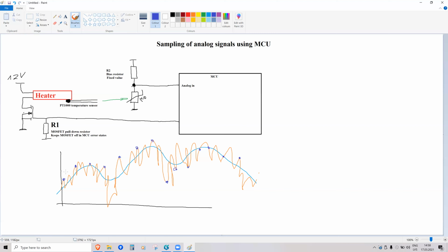And this is also the same in signal processing, that you can accidentally sample the signal too high. So you're sampling and it just happens that you're sampling these peaks. So the signal that you think is the real deal is like this. And then after some time, it samples a different location. And so as you can see, the blue that I sampled with my microcontroller is very different from the light blue, which is the real signal.